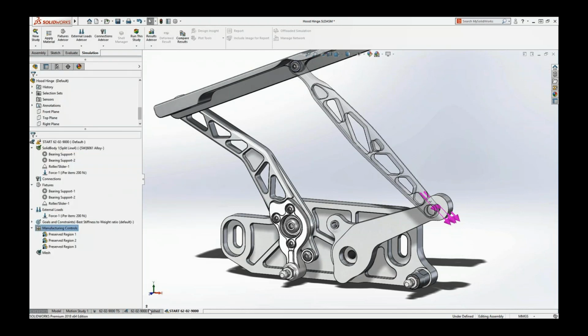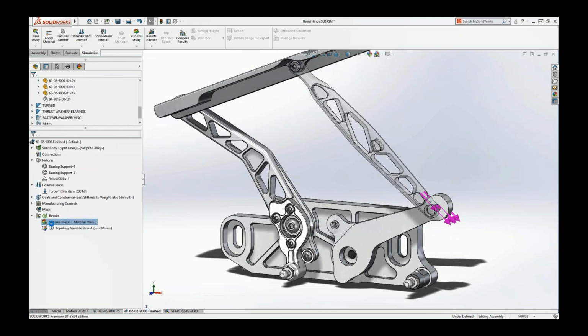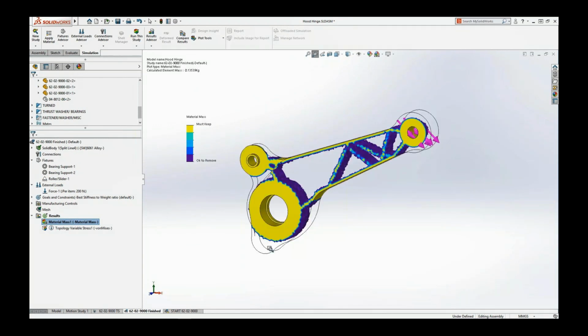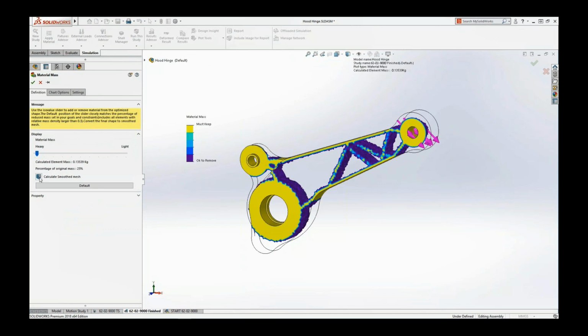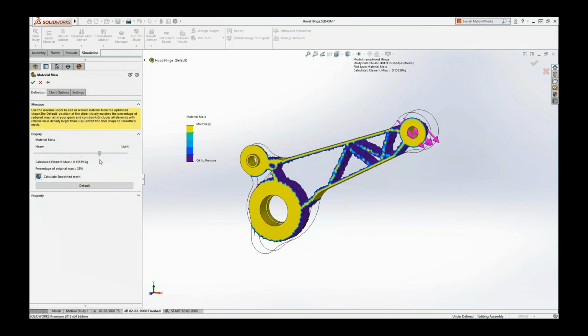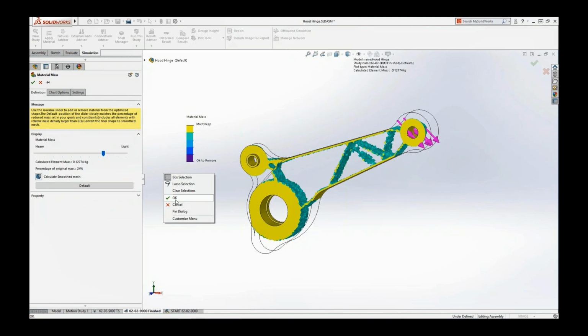So now we can see the final shape. The final shape here is based on the mesh itself. As you saw, there are no dimensions, no parameters that have been defined. So we have just defined the volume from which we want to start, and we can define how much we want to reduce the mass. Also, we can leverage this kind of slider to check more or less if we want a lighter approach or a heavy approach, and so on.